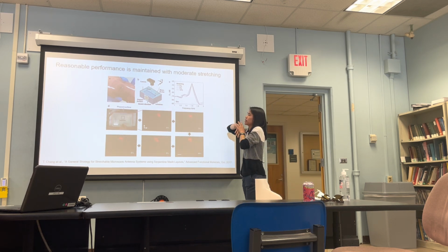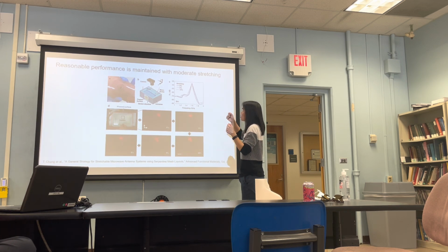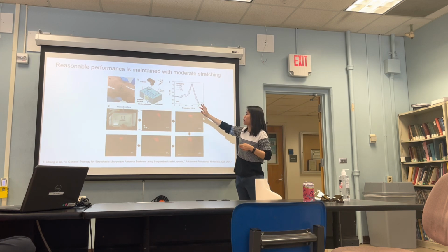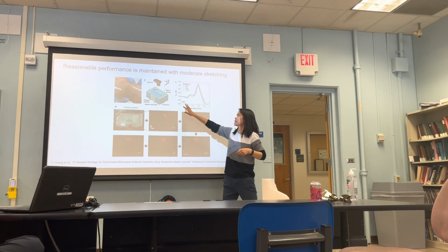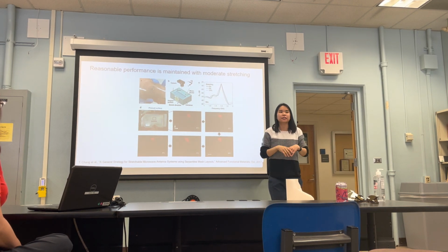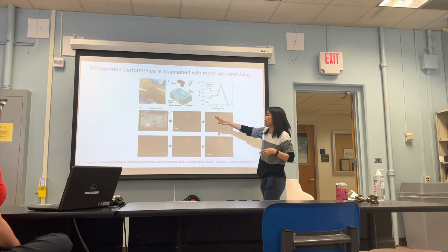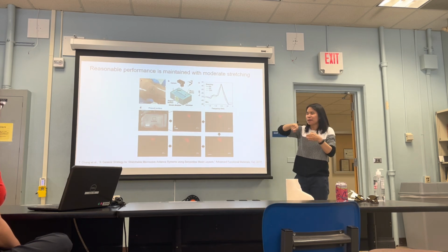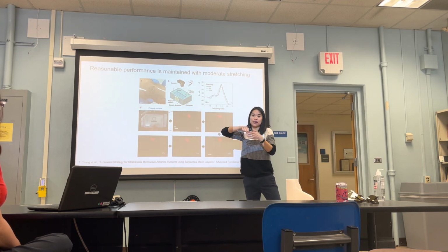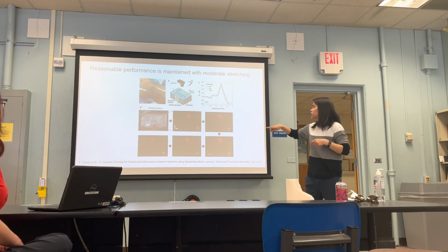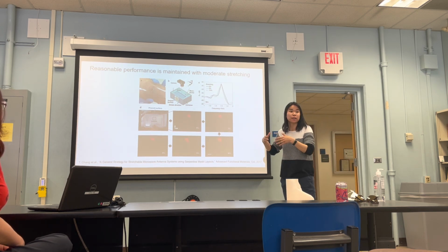The bottom substrate is like a silicone-like material, like a rubber type material. And then you can stretch it. The thinner that substrate is, the more stretchable. And then all that's being shown here is looking at how the properties of that power transfer, for something that was intended to emulate the human body, how well that works when you're doing stretching. And so we swept a little implant device that would light up when it received enough power, and then did a camera on long exposure to show the actual focusing that was happening in the body.